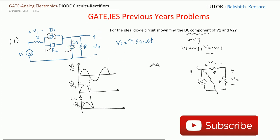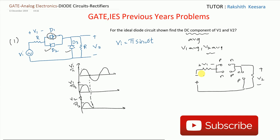See the equivalent circuit here. See, here minus is connected to P, so this will be in reverse bias. Here minus is connected to N, so this will be in forward bias, because minus is connected to N type. And if you observe here, this P type is connected to this positive terminal, so this diode will also be in on state. So this is on state, this is also in on state, and this will be in off state.